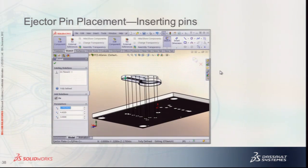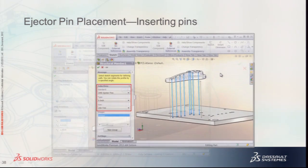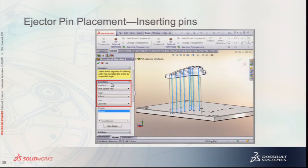And then you can come to your weldments tool. I'll just show a little bit more of how that looks. You can use your actual geometry of your part if you insert that into your assembly. So using the weldments tool, a structural member, you insert that and you can actually select those lines and it places an ejector pin. One of the advantages to doing it that way,